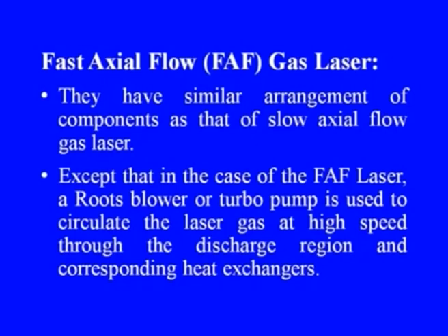In the case of fast axial flow, or FAF, gas lasers, they have a similar arrangement of components as the slow axial flow gas lasers, except that a roots blower or turbo pump is used to circulate the gas at high speed through the discharge region and corresponding heat exchangers.